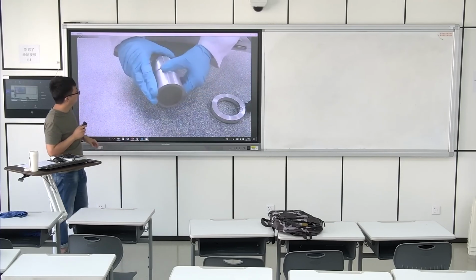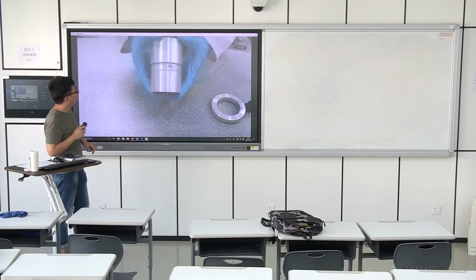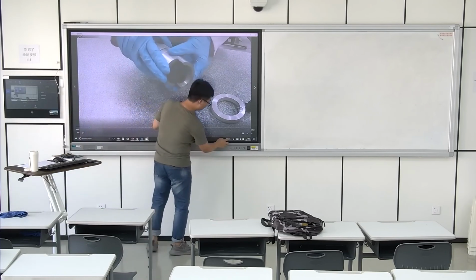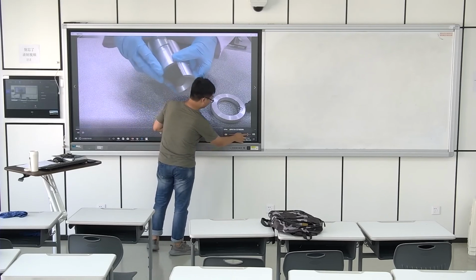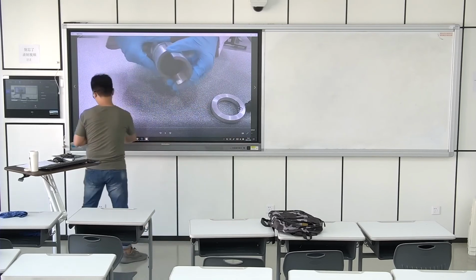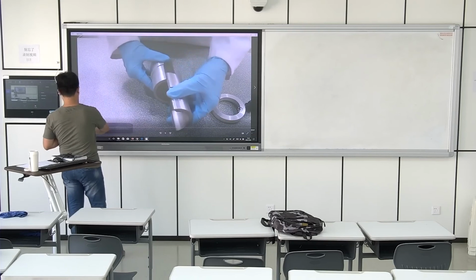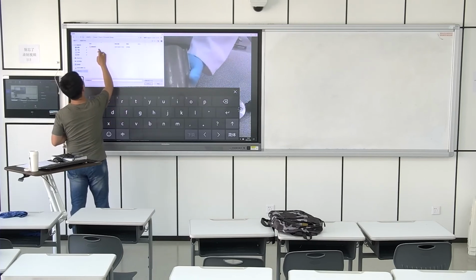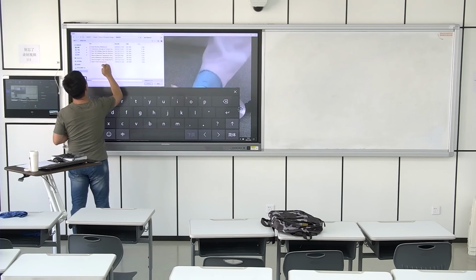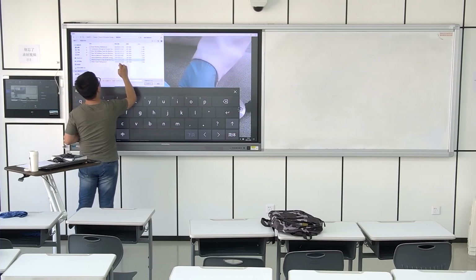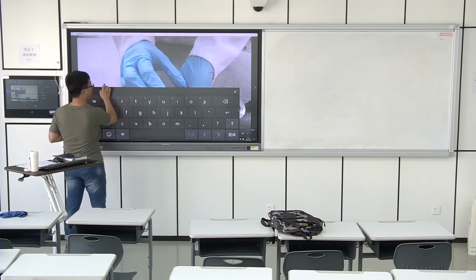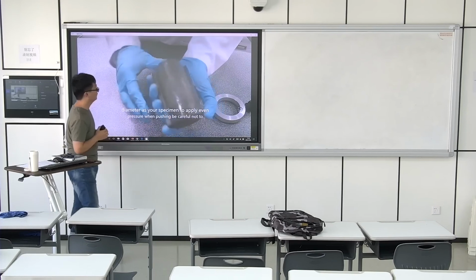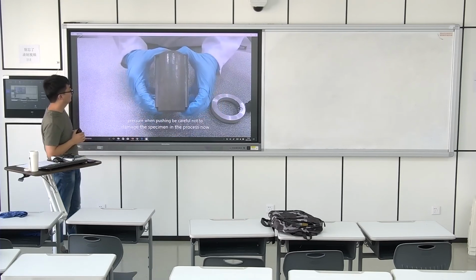In some cases, it can be useful to apply a small amount of non-corrosive silicone grease along the groove of the split mold to help reduce resistance. We recommend the use of PTFE silicone grease. If the specimen is stuck, use a disc the same diameter as your specimen to apply even pressure when pushing. Be careful not to damage the specimen in the process.